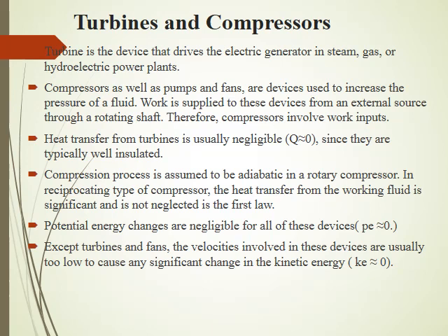Heat transfer from the turbines is usually negligible and they are typically well insulated. The compression process is assumed to be adiabatic in a rotary compressor, whereas in a reciprocating compressor the heat transfer from the working fluid is significant and therefore it cannot be neglected while doing energy analysis with the first law.